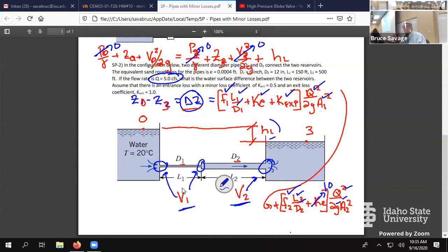So to get the velocity is just Q divided by area. Correct. Yeah, it's just continuity equation where we say Q is equal to VA. Well, now velocity is just equal to Q divided by A. That's the substitution that we put in to turn this into the flow rate. And because it's completely full of water, you can use the whole area. Right. Yeah. This is closed conduit. Pipe is full. It's circular. Otherwise, there'd be another set of constraints that we'd have to bring into play.